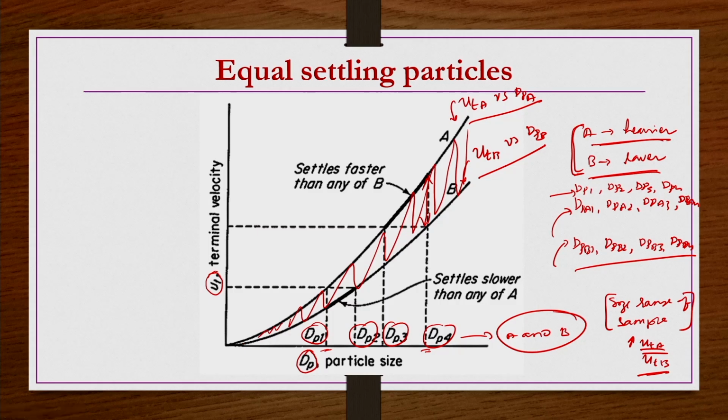If the particles are very small, in the fine microns range, then their settling velocities are going to be almost the same, close to each other, even if one of the materials is lighter and the other is heavier. Because usually under the Stokes regime these settling velocities are going to be very, very small. So that is the one.